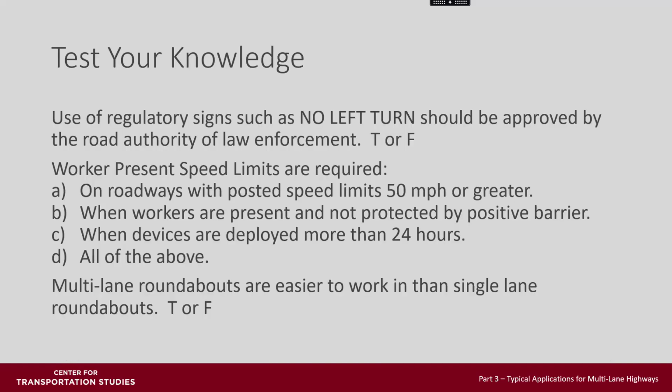Let's talk about what we just covered. Use of regulatory signs such as no left turn should be approved by the road authority or law enforcement. That is true. Worker present speed limits are required on all of the above: roadways with posted speeds 50 miles an hour or greater, when workers are present and not protected by positive barrier, and when devices are deployed more than 24 hours. Multi-lane roundabouts are easier to work in than single-lane roundabouts. That is true.